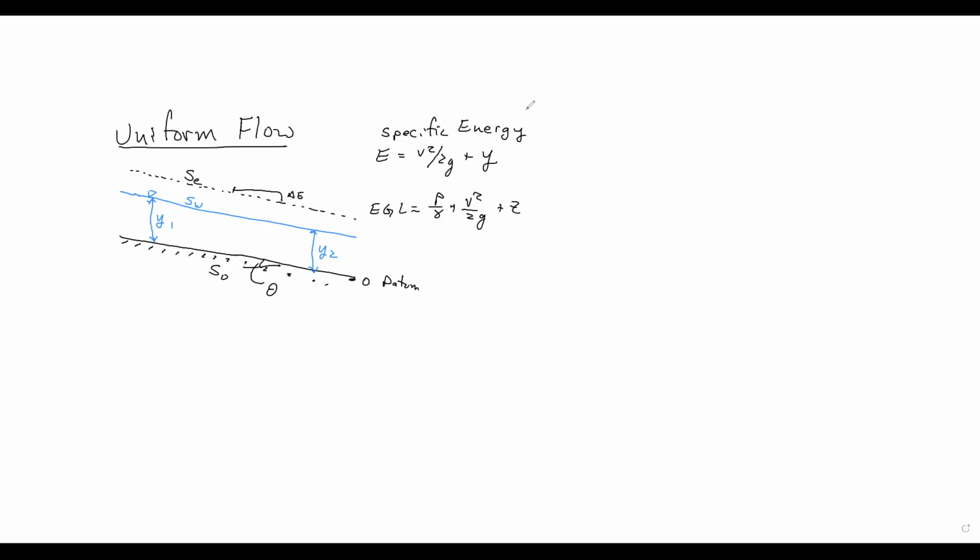This will be our hydraulic grade line, which is equal to P over gamma plus z. And we'll note that P over gamma is going to be equal to the depth, right? The depth is just our pressure. You go to the bottom of the channel, that is the overall pressure from the water. So we do have pressure in there, but it's not necessarily driving the flow.